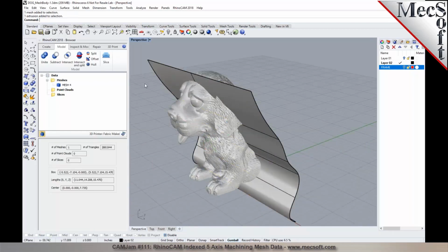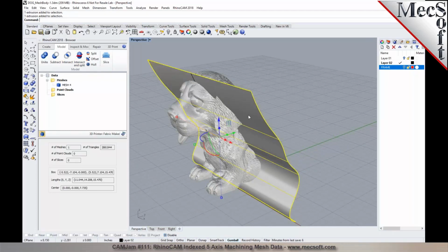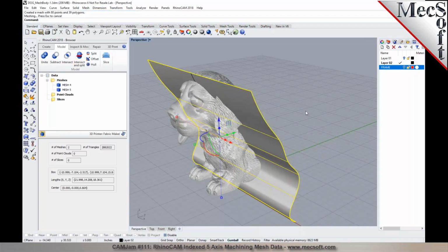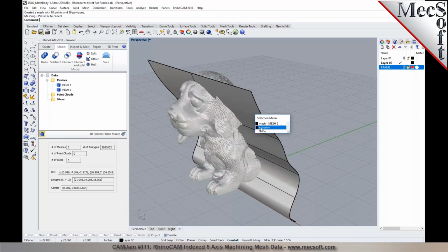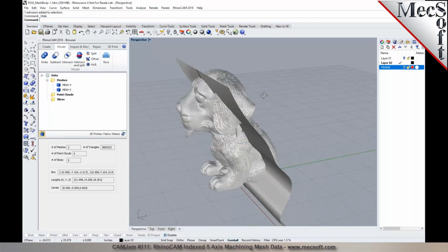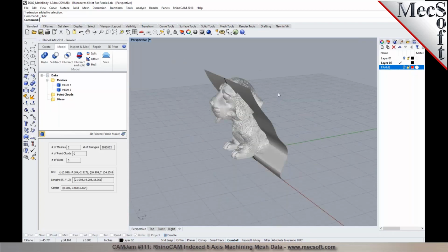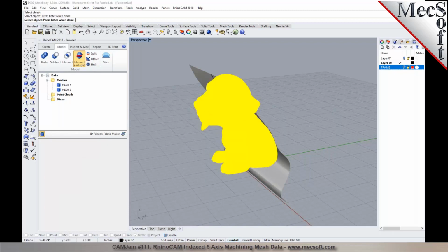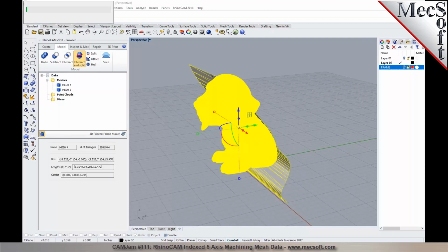So you can see that the mesh split, for some reason in Rhino, it didn't work out well here. So let's go ahead and convert this to a NURBS. Okay, so I have now 2 meshes in here, right? So now I can use an intersect and split. Select the objects, the mesh to split right here. And now I'm going to pick this cutting mesh right here.